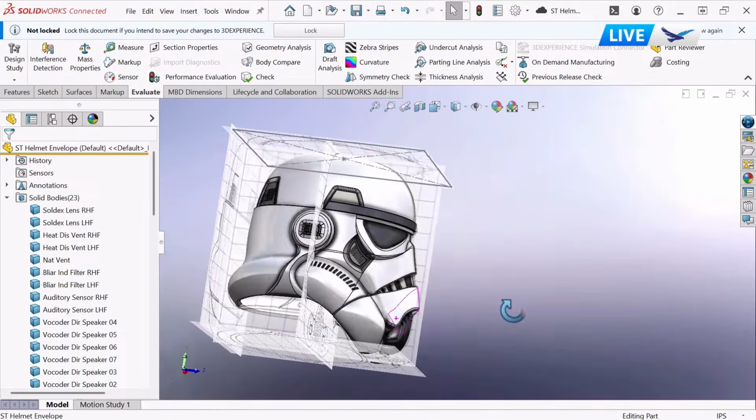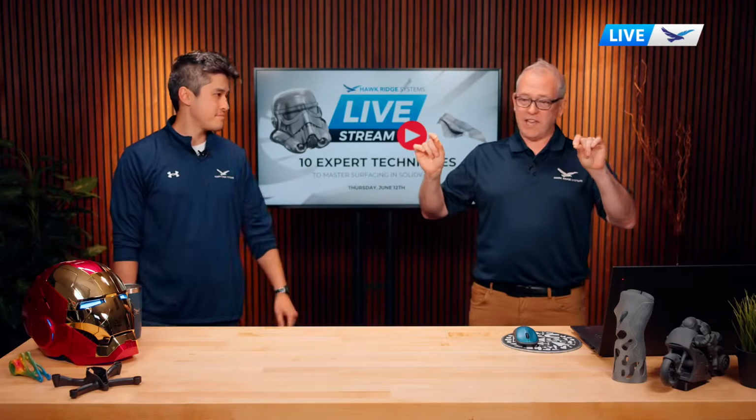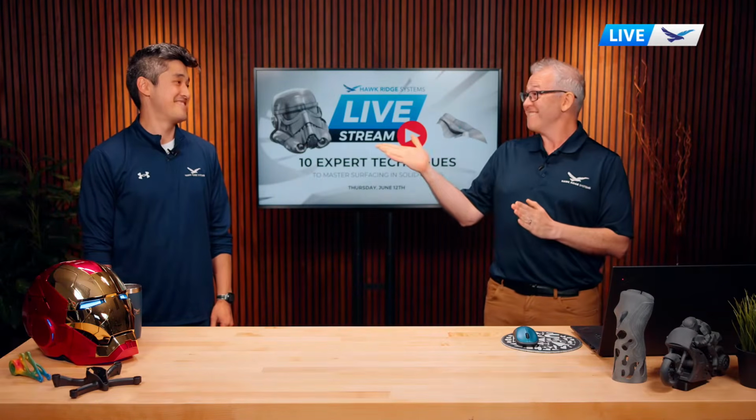What I did here is I took the right plane, front plane, top plane, and so on. I created a new plane there, placed the planes where I wanted them, put sketch pictures in each one, and lined them up. You can resize them. If there's a precise dimension you need to hit, there's a line when you place that sketch, and you say from this point to this point is going to be 10 inches, and then it will scale the image to that size. We could have scaled it to my head. Yes.